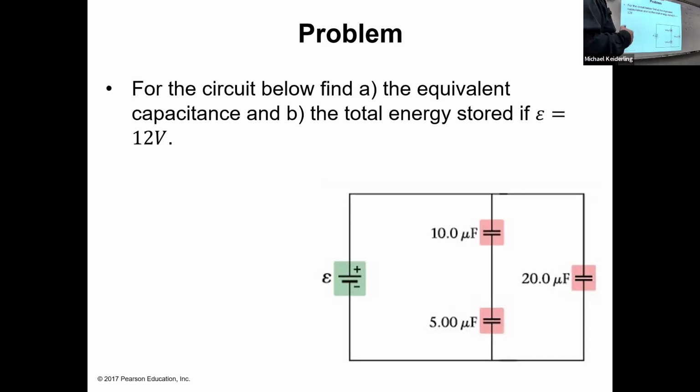So remember, just like with resistors, you could split it into parts and combine them. And capacitors in series, you add the inverses and take the inverse. Capacitors in parallel, you just add.